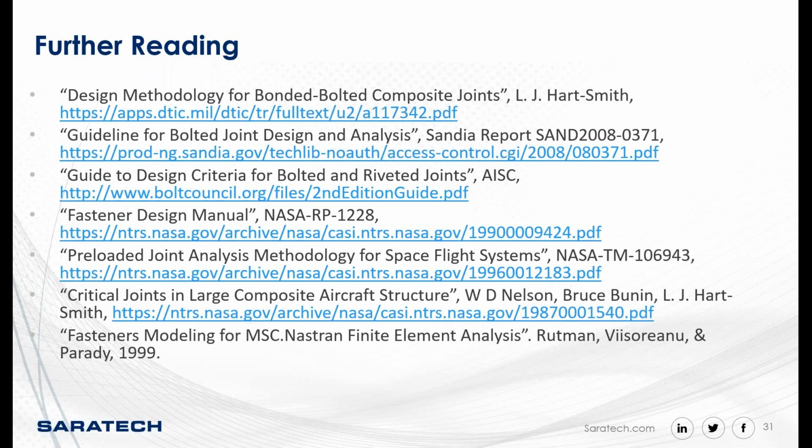And our next question is, when we tried fastening a solid mesh to a plate mesh with beams, RBE2 spiders, contact, and preload, the plates kept ending up inside the solids, and not by an amount attributable to rounding or display errors. Is there a way to prevent that, or is the solution to avoid modeling 2D to 3D contact plus preload joints? Well, that kind of surprises me, because contact should prevent them from passing through each other. Now, when you do contact between 2D elements, you have a couple of different options